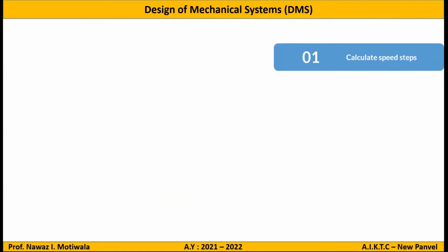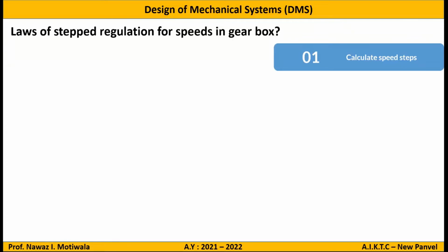Okay, so the first step, as I mentioned, will be to calculate the speed steps. There are some laws of step regulation which are followed by all the companies, so that if I go to the market I can replace it with standard parts. So now we have to study what the different regulations for speed in the gearbox are.